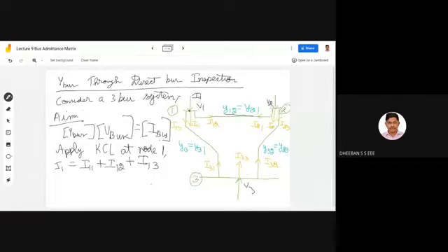With respect to admittance, how can we write I11? Here it is the self admittance, so 11 corresponds to the self admittance. As per the definition, you have to subtract the voltage from your reference voltage. So it will be V1 minus V0 into Y11, where Y11 corresponds to the self admittance of your bus 1.